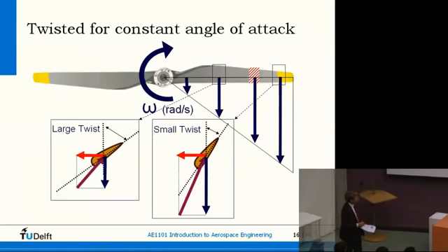And the vertical direction is determined by your airspeed. So if you want to do this right, if you have a fixed propeller, that would only work right for one airspeed. And that's why you want to twist the propeller to compensate for airspeed or rotational speed to make sure that the angle stays right. So that's why we have variable pitch. It covers changes in rotational speed and in airspeed, and avoids the problem that a fixed propeller is only optimized for one condition, one ratio of airspeed and propeller speed.